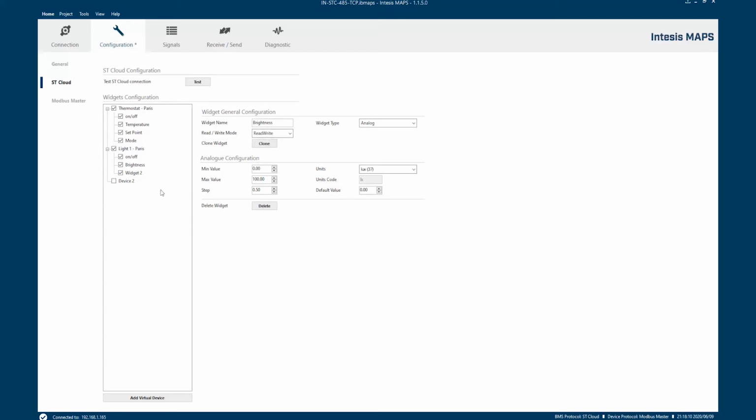Something very cool here is. Now we're going to be creating the illuminance, okay? The illuminance is very similar to the brightness. The configuration is pretty much the same, but we have to change some values. So what we can do is we can click here and clone this widget. So cloning this one, we are going to devices to add 1. So we click here to apply, and here we have brightness 0. This brightness 0, we said, is what's going to be illuminance.